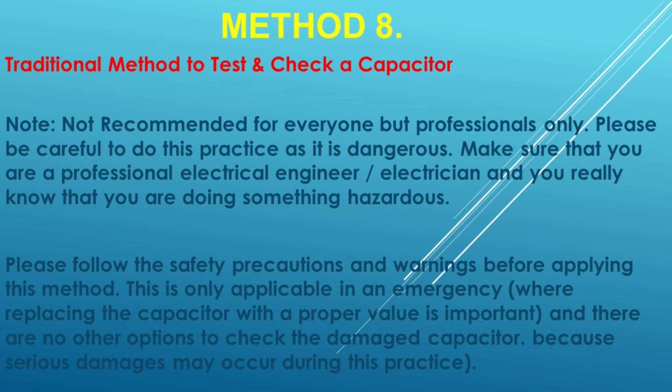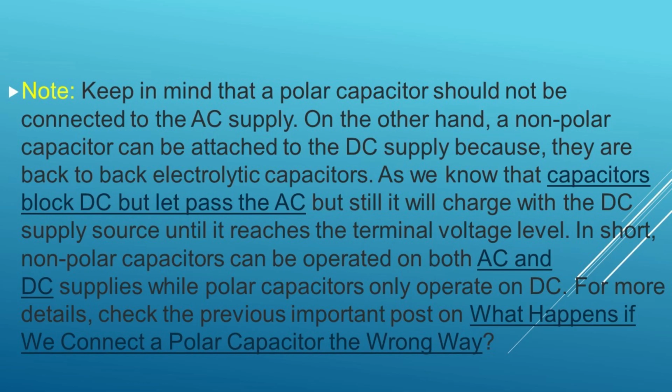In case of absence of a DC source, like batteries, for high-rated capacitors, i.e. fan capacitors rated for 3.5 µF, 120, 230 or 400 V, you may use 120 to 230 VAC, but you have to connect a series resistor, say 1K ohm to 10K ohm, 5 to 50 watts, between the capacitor and the 230 VAC supply. This way, it will reduce the charging and discharging current.